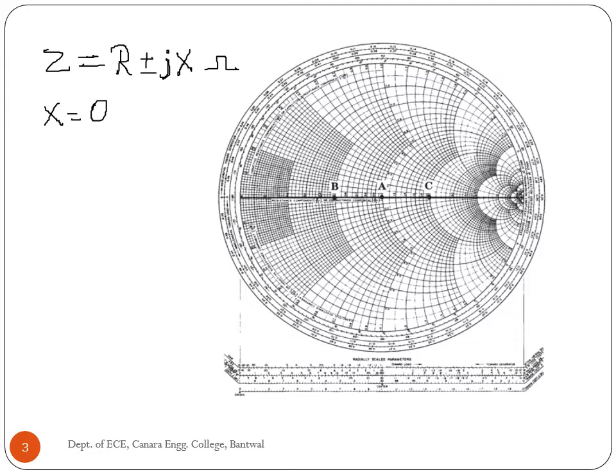In order to make the Smith chart universal, the impedances along the pure resistance line are normalized with reference to system impedance. For most microwave RF systems, the system impedance is standardized at 50 ohm. To normalize the actual impedance, divide it by the system impedance. For example, load impedance is given in ohm.